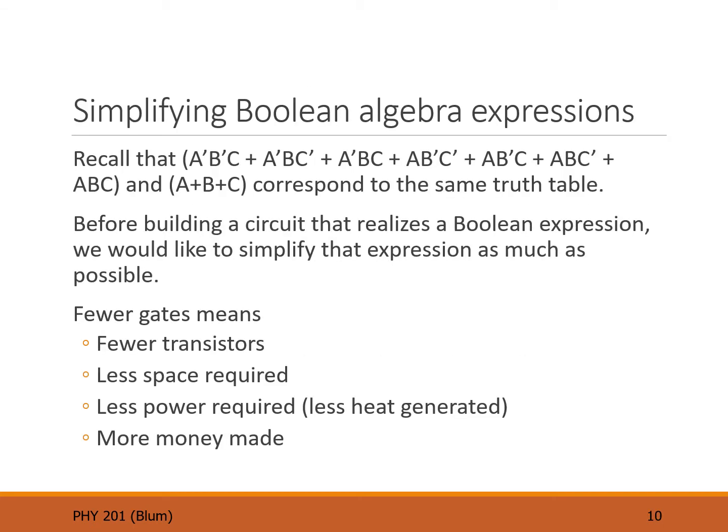Previously, we considered a somewhat extreme example where the output of a 3-input truth table, the first output was a 0 and the rest were 1. So we can take a sum of products approach and we would have 7 minterm expressions, or we could take the product of sums approach and we would need 1 ORed expression, 1 maxterm.